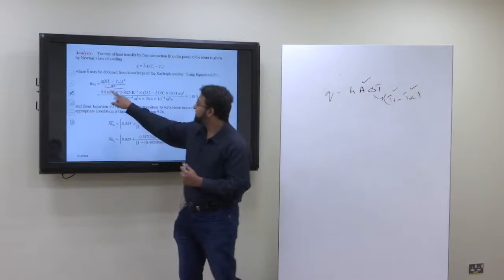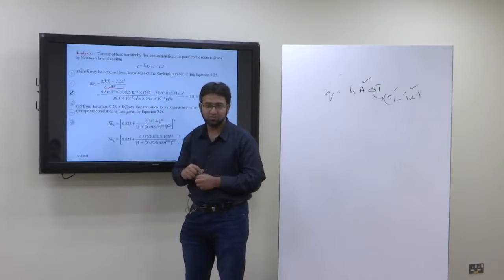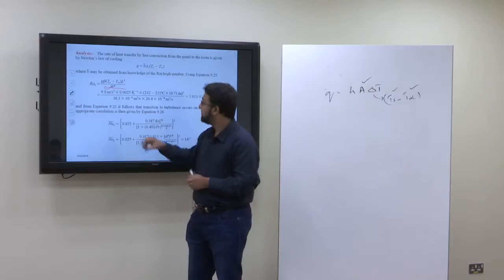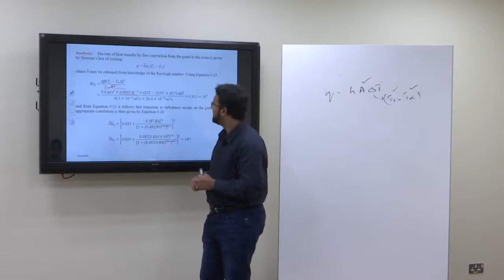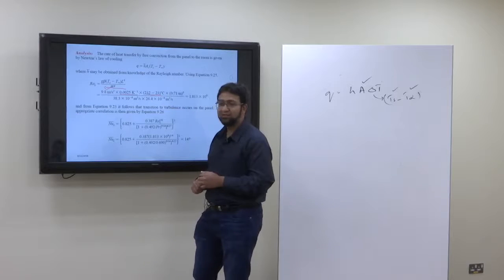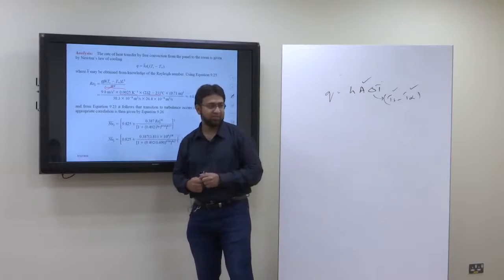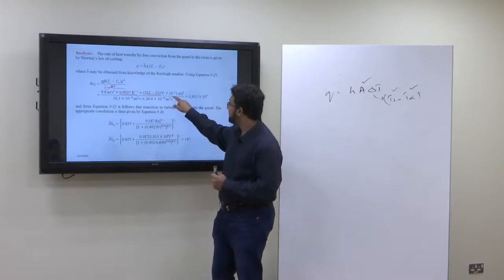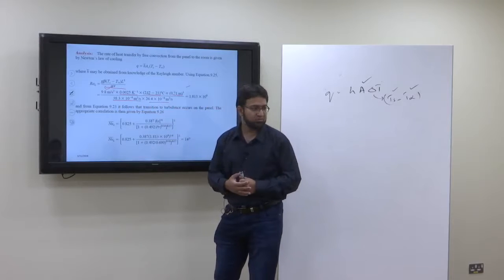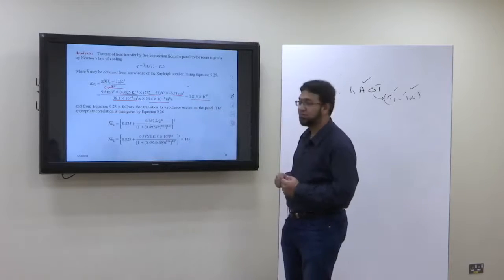So here we have g 9.81, beta 1 upon Tf, but Tf should be in kelvins. If you put it in degrees centigrade, it's a mistake. So that comes out to be this. Ts minus T infinity multiplied by L cube. Which length are we talking about? That will be the height, that's the direction of flow. So L cube divided by alpha and mu. All these properties are known. So based on that, we find out that the Rayleigh number is 1.813 times 10 to the power 9.